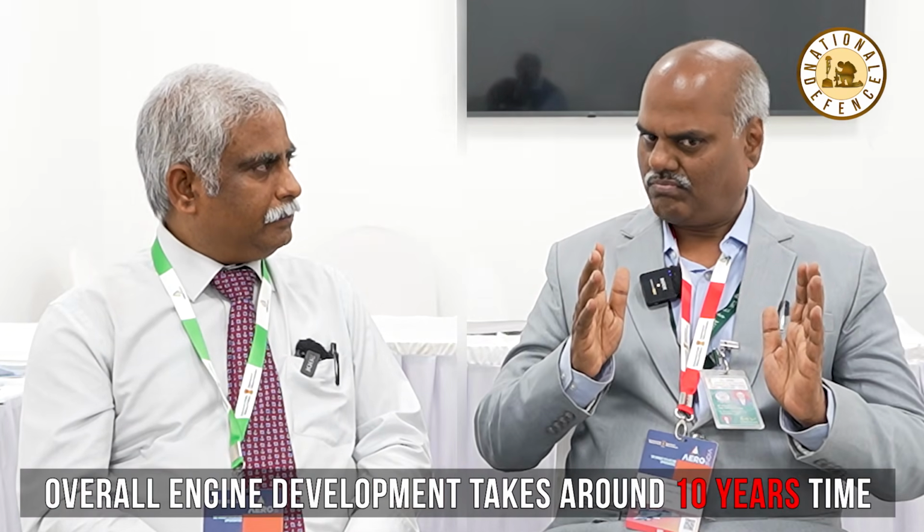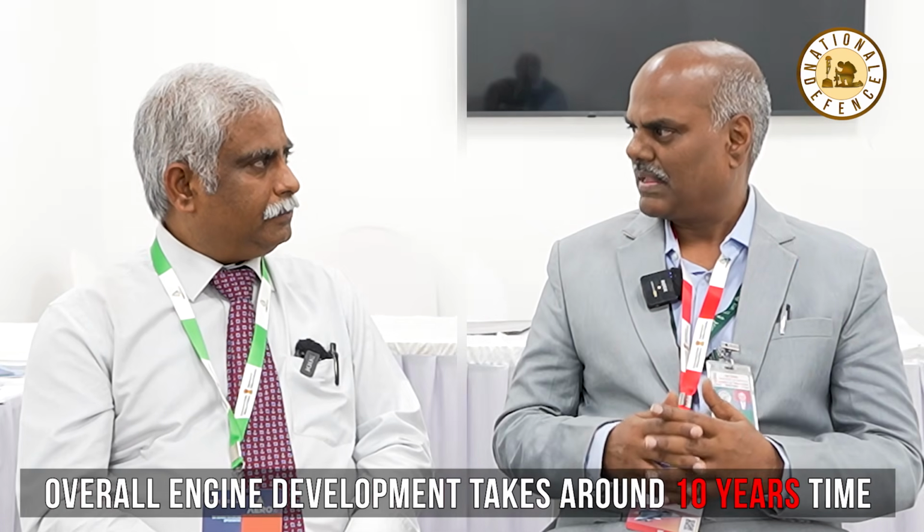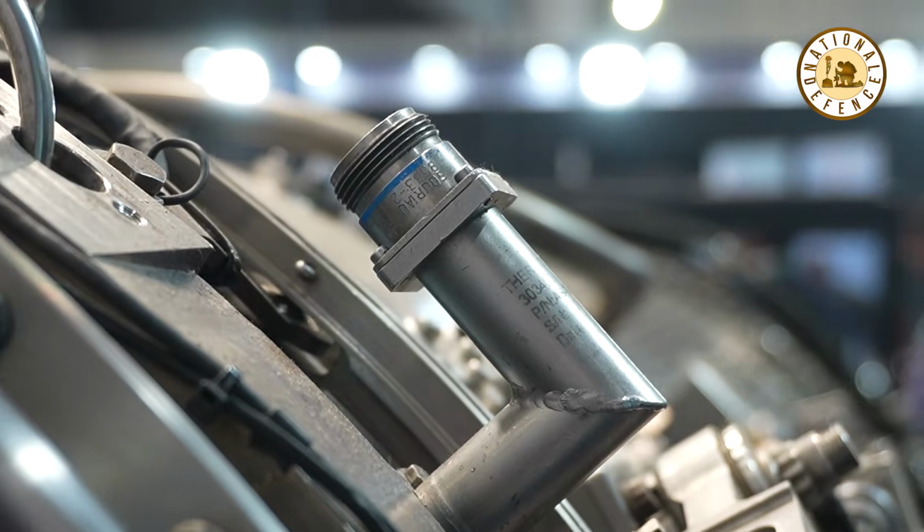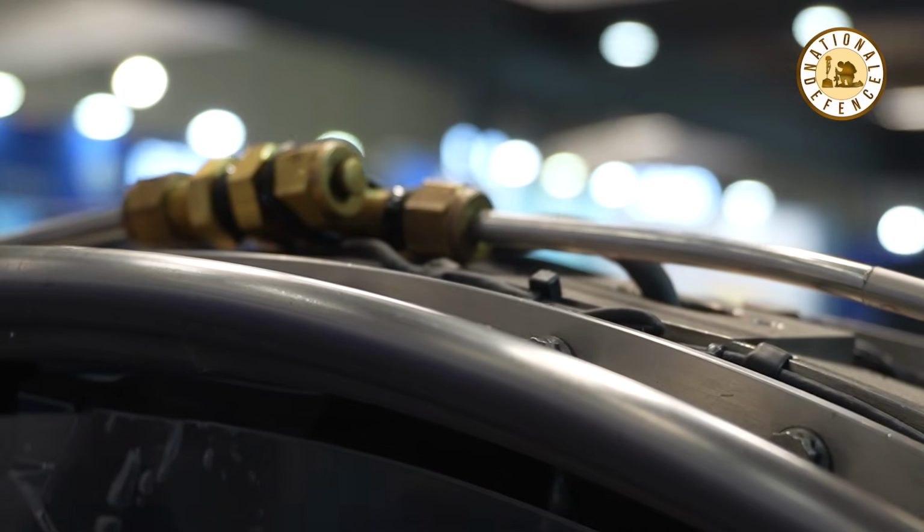See, one design we call aerothermostructural design. That takes 1.5 years, 18 months. From there, detailed design will be starting. From there, the basic thing will be, as I said, single crystal castings and machining. That development of the single crystal process, getting the castings, then machining, a lot of things will be there. Small tiny holes will be there that have to be laser drilled, and that will be a hollow blade. One ceramic core will be there. Once you take out the core, vacuum brazing has to be done.